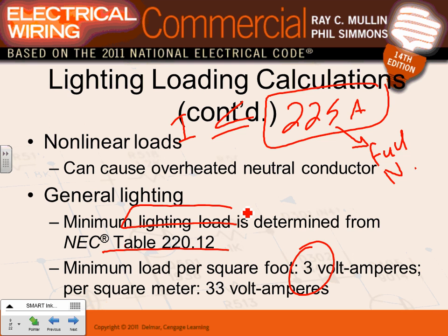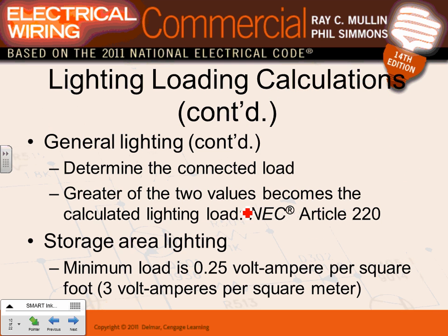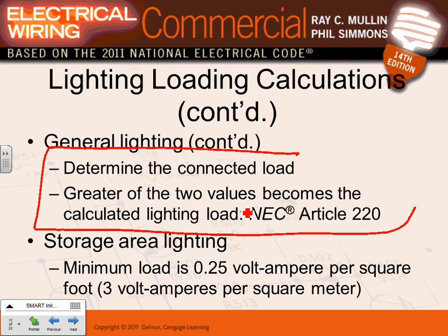Are you familiar with that one, right? 3 volt-amps per square foot. Or you're going to compare it. You're going to determine the actual connected load. You're going to take the largest of these two. Isn't that what you did with me? You're going to take the connected load, the actual load, and take the greater of the two values